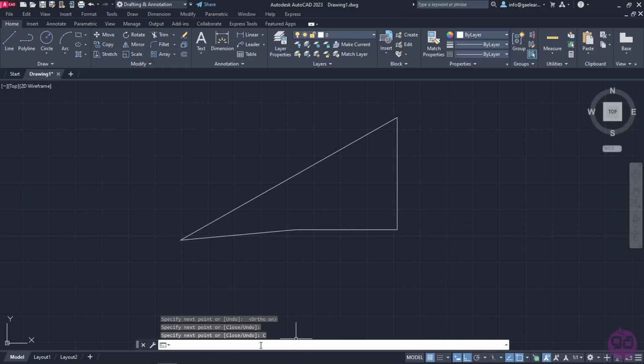Once I click on it, a line connecting the first and the last lines I drew is automatically created. Now I have a closed profile. I will select one of those lines and notice that they are indeed three independent line segments that can be modified separately.